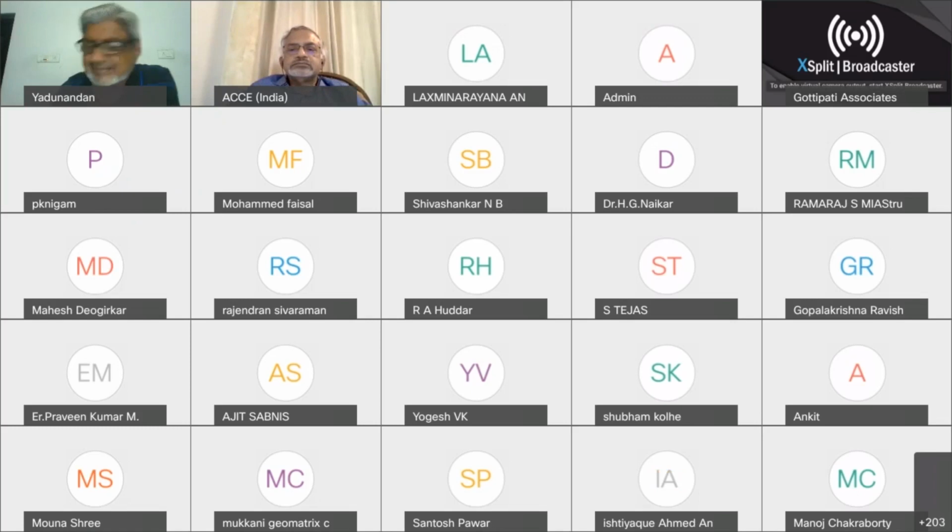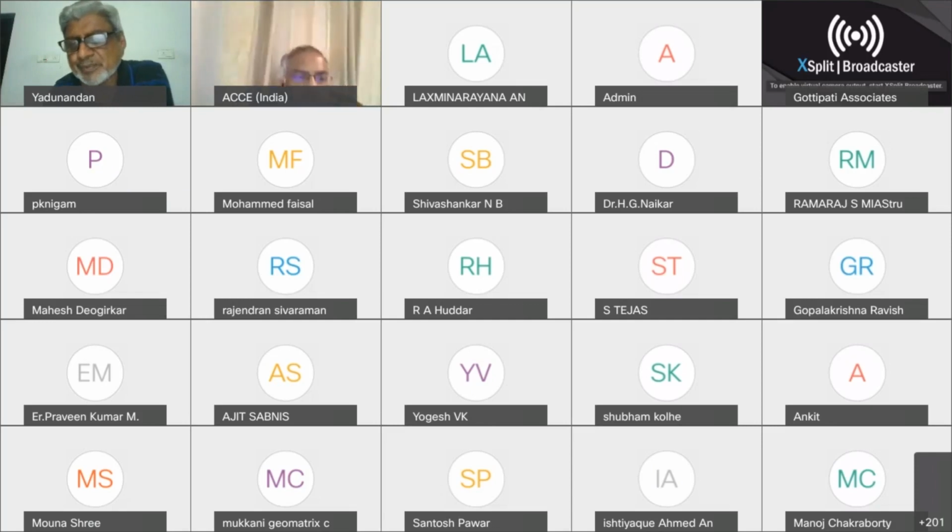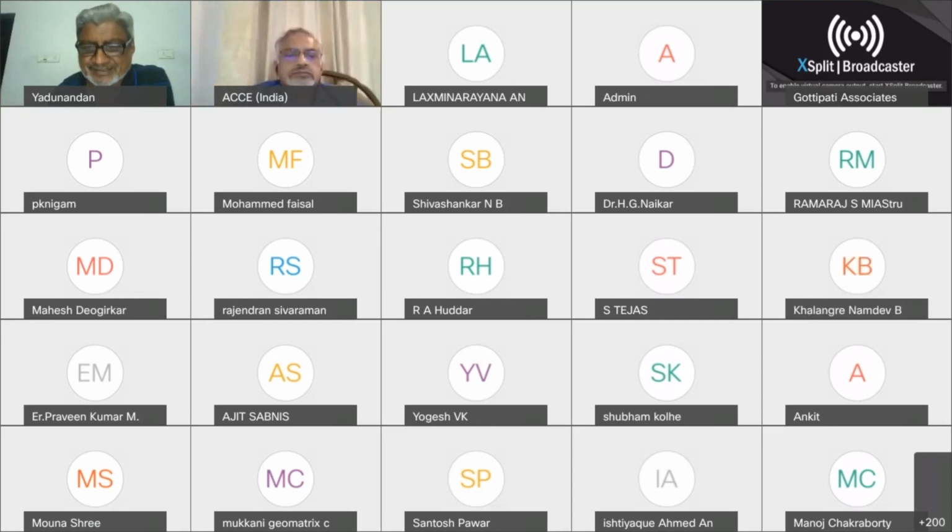I didn't get what the question was. What I am telling is we try to control the sway of the structure to an extent where it is possible for us to have more rigid columns. Use the sway effect and check the values within the columns so that they are not acting as slender columns. That is more useful. Slenderness reduces the capacity of the column to a large extent.